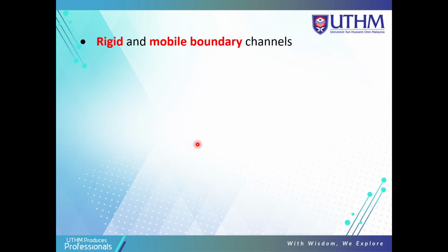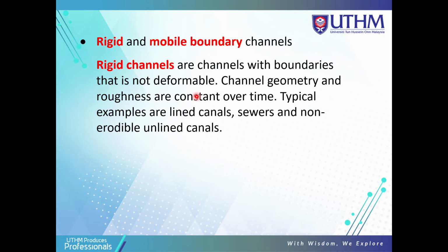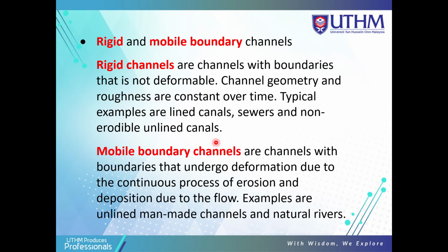Rigid and mobile boundary channels. Rigid channels are channels with boundaries that are not deformable. So this is the definition of rigid channel. Channel geometry and roughness are constant over time. Typical examples are lined canals, sewers, and non-erodible unlined canals. So this is the rigid channel.